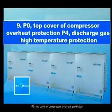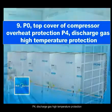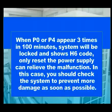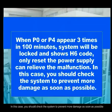P0, top cover of compressor overheat protection. P4, discharge gas high temperature protection. When P0 or P4 appears 3 times in 100 minutes, the system will be locked and shows H6 code. Only resetting the power supply can relieve the malfunction. In this case, you should check the system as soon as possible to prevent more damage.